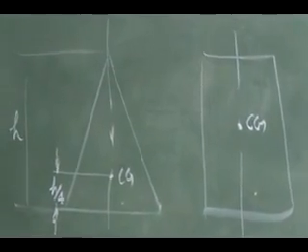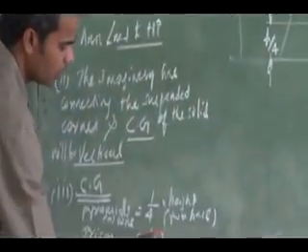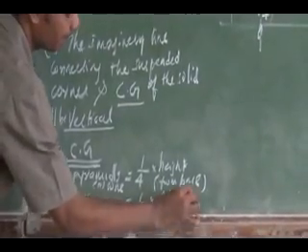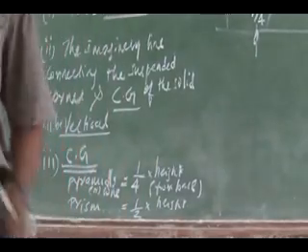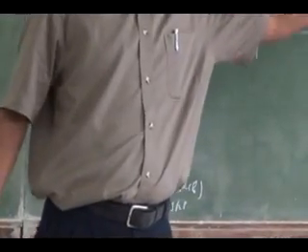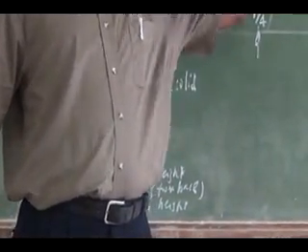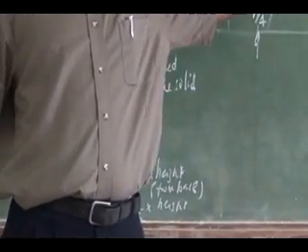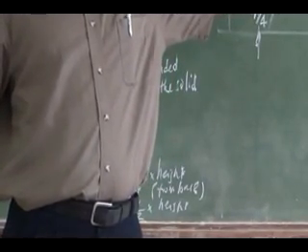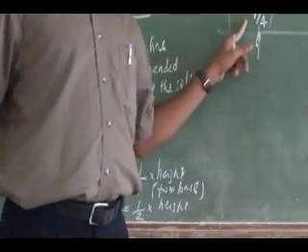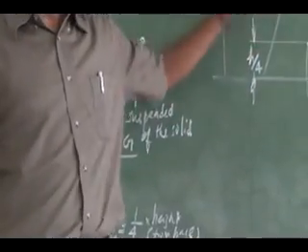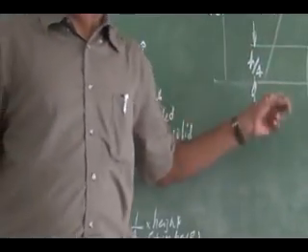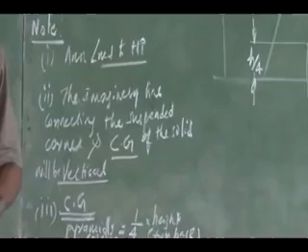So I can say 1 by 2 of its height, on the axis. The CG will be on the axis, at 1 by 2 of the solid's height for prisms and cylinders, and at 1 by 4 of the height from the base for cones and pyramids.